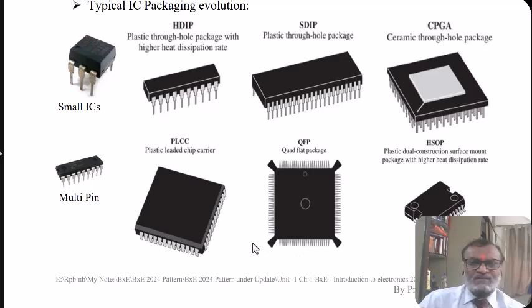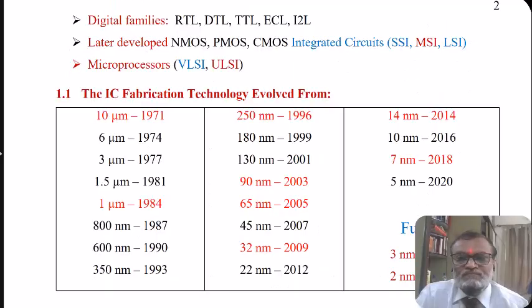Whereas some of the ICs nowadays can have pins like QFP. These devices don't have through hole pins. They are folded and soldered on a single side of the PCB. These are also called SMD devices, that is surface mount devices. Those are used nowadays in electronic circuits and boards.